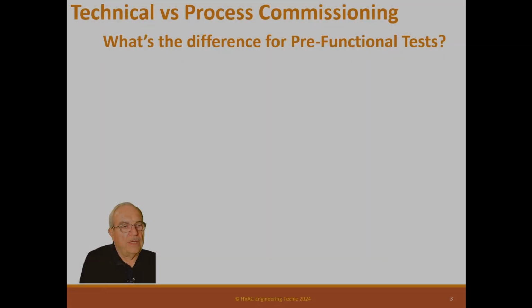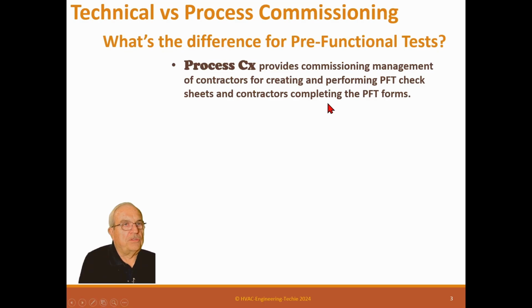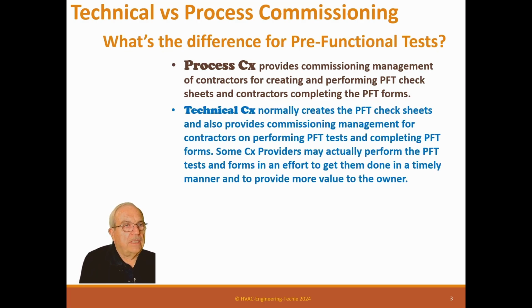So now we'll start talking about pre-functional tests. What's the difference for pre-functional tests? Process commissioning provides commissioning management of contractors for creating and performing PFT check sheets and contractors completing the PFT forms. Technical CX normally creates the PFT check sheets and also provides commissioning management for contractors on performing PFT tests and completing PFT forms. Some CX providers may actually perform the PFT test and forms.